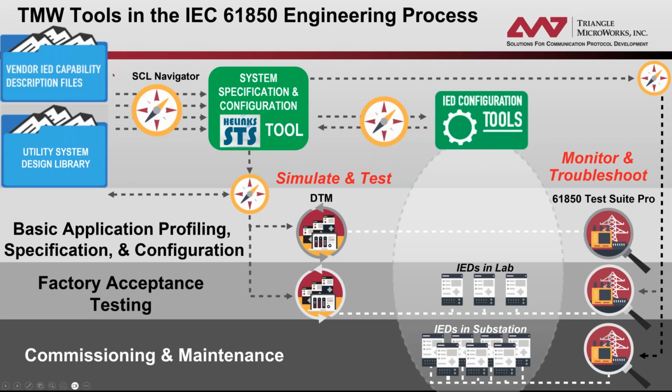So we begin here not so much with the specification, but with our different IED capability files or ICDs. You're able to validate those or even create ICDs with the tool that I'll be showing in a moment, SCL Navigator, which is an SCL viewer. You're going to load these into your system configuration tool right here. And then that's, like I said, where a bulk of your time will be spent designing your actual system.